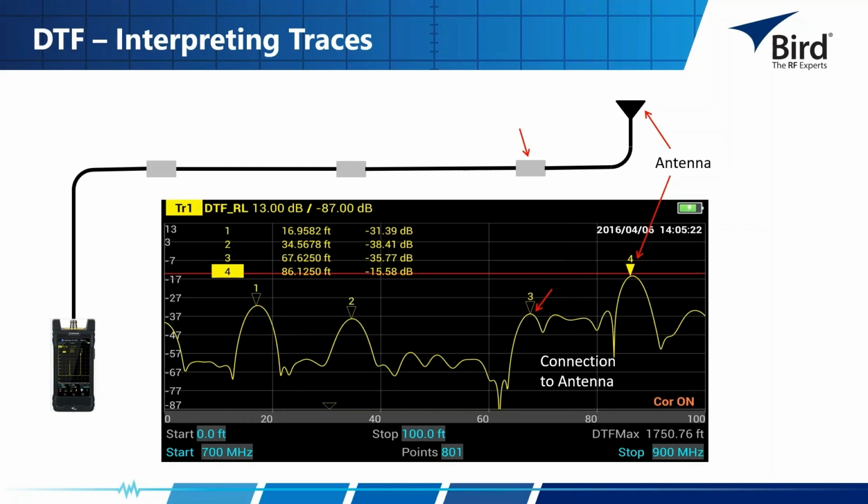Remember the previous slide, we were at about -19 dB? Well, I went out and I took a look to see what the problem was. Here, my connector was not real tight. It was loose. I fixed it. All I did was tighten up the connector. We're down well below the -25 dB I wanted to be at, and I'm actually at -35.77 dB.